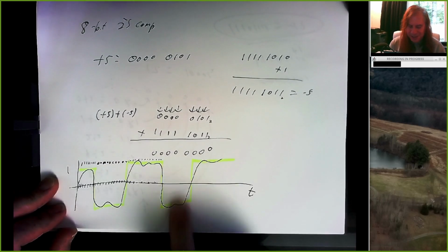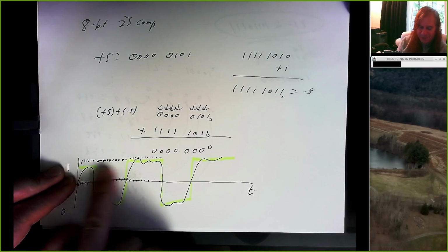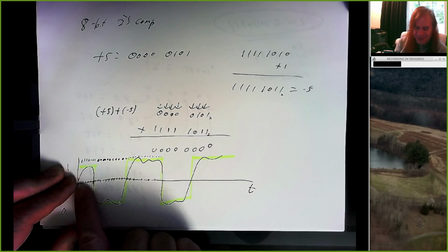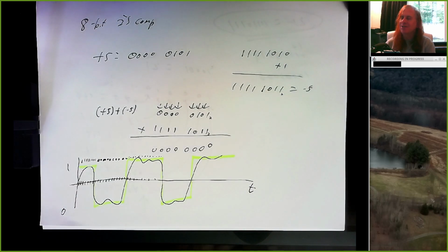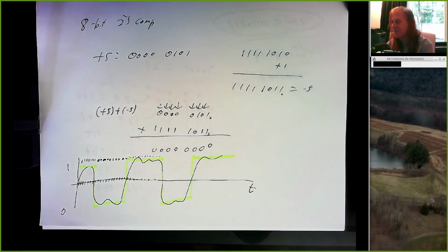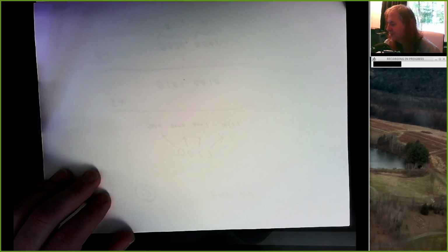And you could actually take a waveform like this that represents audio, and listen to it, and then you could code it with this single bit, 1 and 0, high and low, and take that coded representation and produce this square waveform and play it back, and it will sound a little bit like the original, right? Now with just a single bit approximation, you get a really, really rough version of your original waveform. But if you use a few bits, we can improve that. So how would we do this analog to digital conversion if we had more than 1 bit available?